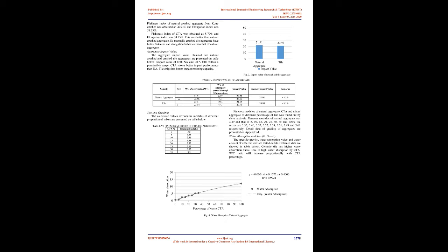Floor and wall tiles from tile suppliers are collected and then crushed by manual hammering method to make coarse aggregate. B. Material properties and specimen preparation. Cement. Cement used for the tests is Shivam OPC cement. The tests on cement were carried out based on IS 4031:1998.